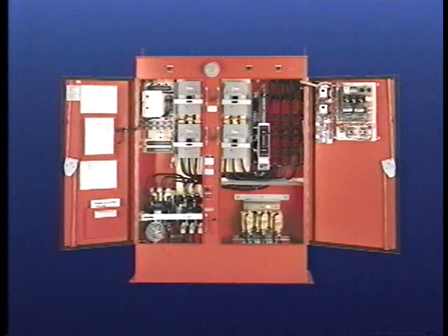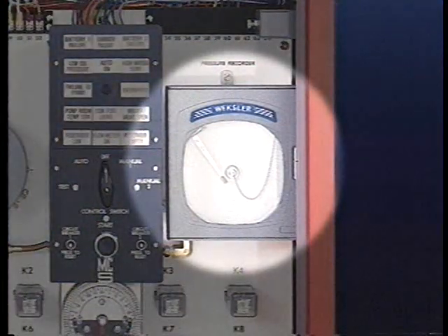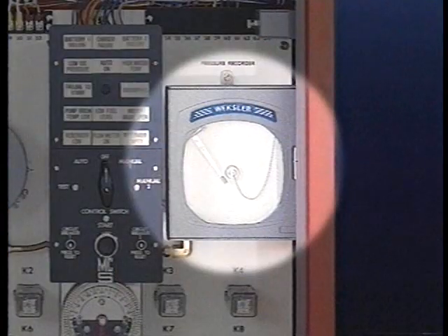Fire pump controllers can be arranged to automatically start the pump at specified times and allow it to run for the minimum time required in the standards. Controllers can have automatic chart recorders or electronic means for recording the pressure output of the pump. These are valuable features because the pump can then be started at off hours, thereby reducing the staff required for testing, as well as eliminating the disruption to operations caused by the noise of the pump and the driver operating. The chart recorder, or electronic means to record the tests, is also an easy way to document that the pump has been tested and is functioning properly.